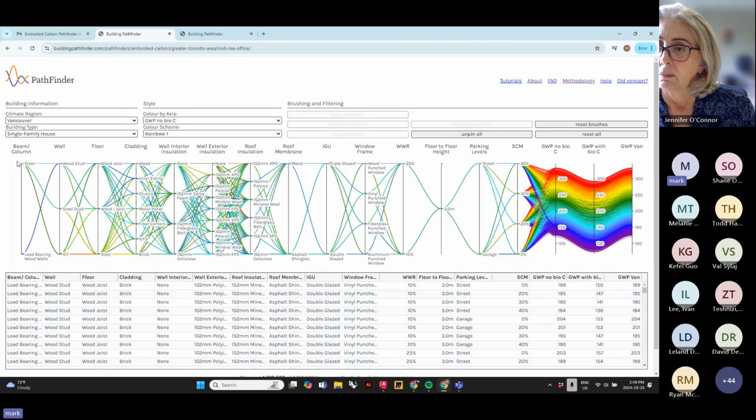Now, the one thing I'd emphasize is that with LCA, when you're looking at the embodied impacts, there's this catch-22: in order to do an embodied impact study using these more detailed tools, you have to have a detailed design. But by the time you have that detailed design, the team is not flexible to make decisions on those systems. They've already locked into their floor slabs and wall slabs by the time you come to tell them that they made a bad decision.